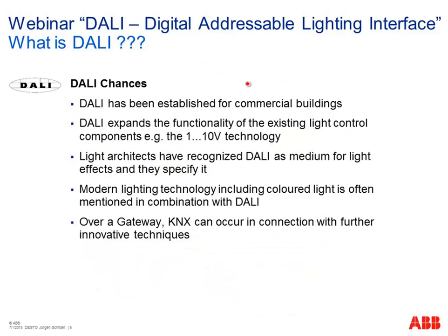DALI has already been established for commercial buildings, so it's in use in a lot of commercial projects. And as already mentioned, it replaces or expands the 1 to 10 volt technology. This will be more and more replaced. Additionally, it's recognized by light architects for any kind of special lighting, light effects, colored lighting, for example.